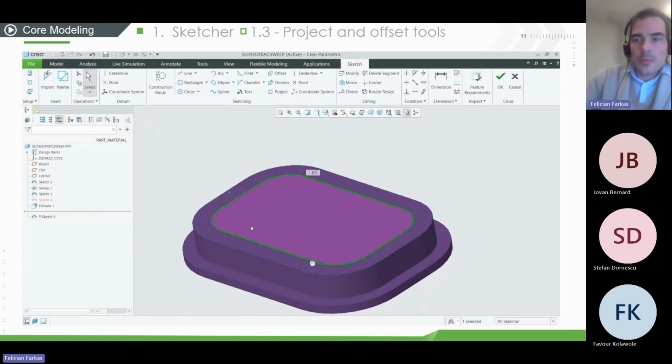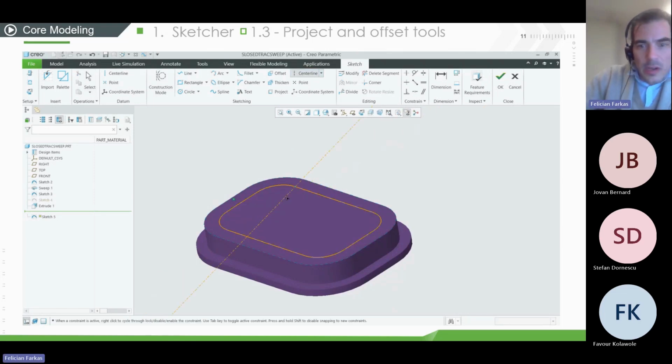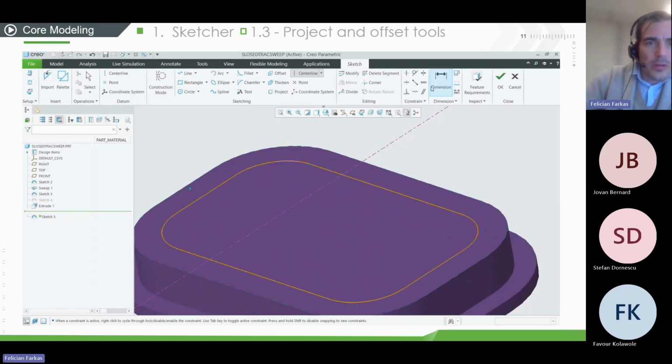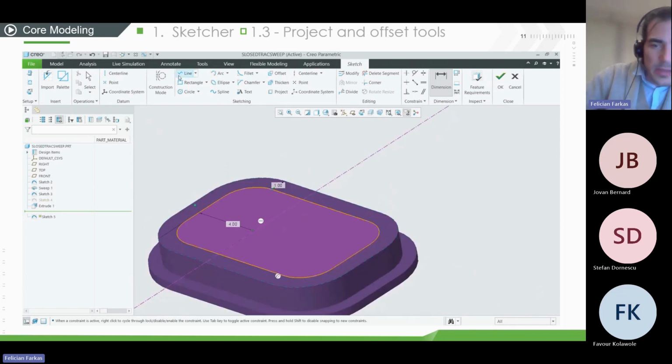And in Creo 10, when we're creating a new geometry and constraining it, the individual entities will be exposed and become selectable. I create a center line here and want to give a constraint to it by giving a dimension, and you can see that dotted red line appears and I can make my dimension from the individual entity.